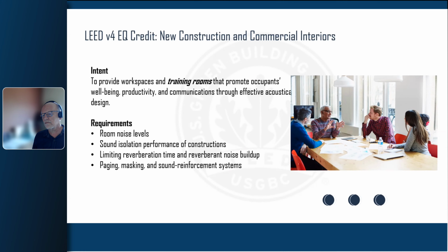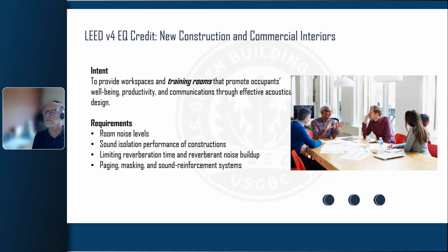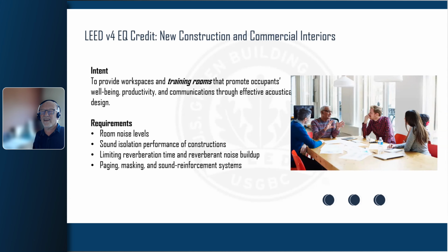Excellent. And let's see if we could squeeze one more question or so. Do you see a difference between a hollow metal door versus an insulated door? Is that a big difference or minor? It's a big difference. A hollow metal door is really not designed as an acoustic door. When you use, let's say, an 18-gauge honeycomb door, and even if you put seals on it, you're probably not going to exceed STC 25. Again, that may be sufficient.